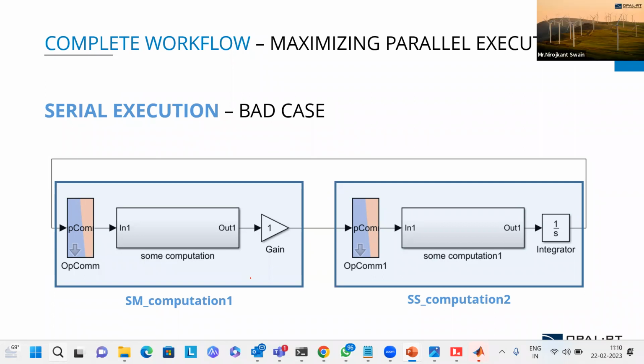Okay, you are using these two workspaces. One thing. Another thing, I'll show you how to script your MATLAB .m file. It's a simple concept. In model properties, you will go to the preload function and place that file name. It will call it. Sir, can you show how it is done? I'll show you, don't worry, just be patient. So in model properties we have a preload function call, and there we have to declare the .m file. Yes.